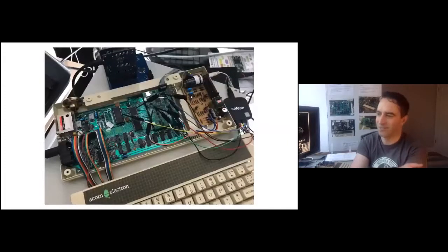So I plugged it in, and nothing happened. No video output. I didn't have a scope at the time, I had a logic analyzer, the Saleae unit you can see there. But no video, so I managed to blink the caps lock LED so I could tell that the FPGA was running, but caps lock is just a GPIO basically. So there were all sorts of things that could be wrong.